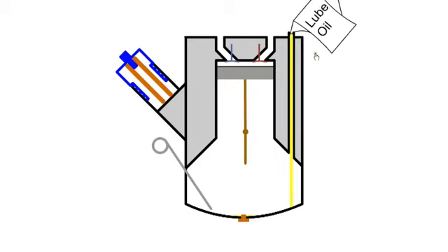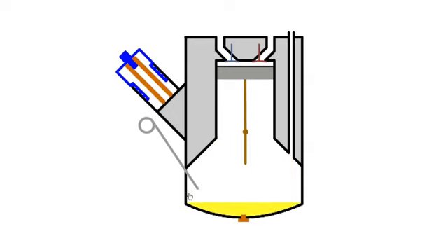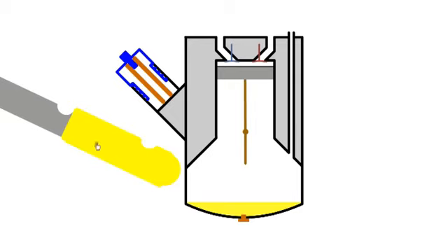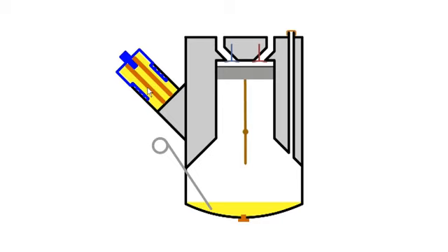The sump is now filled slowly with new oil to the desired level. When the oil is allowed to settle, the level can be checked with a dipstick. The level should be at or just under the high level mark. Fit the oil cap and clean any oil spills. When the engine is started, it will fill the filter with oil. Check the oil level and again, be careful not to overfill.